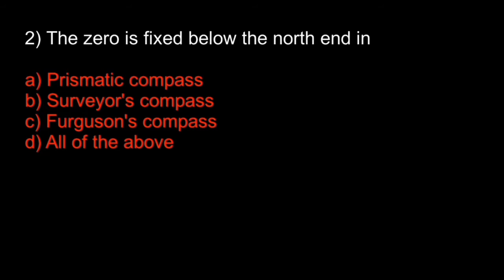Where can we use this compass survey? If the surveying area is large, chain surveying is not adopted for surveying, rather compass surveying is employed. If the plot for surveying has numerous obstacles and undulations which prevent chaining, compass surveying is used. If there is a time limit for surveying, compass surveying is usually adopted.